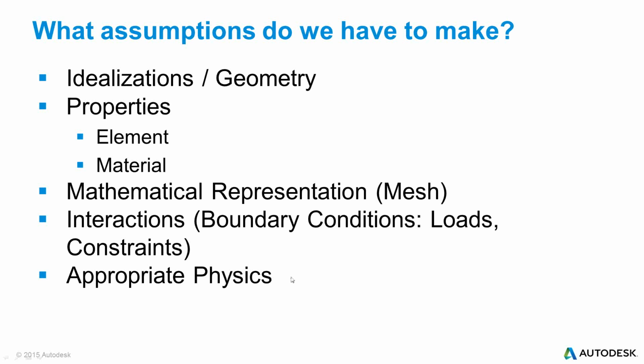We're also assuming that you're using the appropriate physics, that if I have a nonlinear problem, I'm really doing a nonlinear analysis. If I have a dynamics problem, I'm doing a dynamic analysis. So those are all assumptions. Any of them you make, write them down, put them in the report.